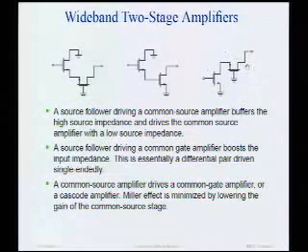And essentially, this second device is just acting as a current buffer, and takes the current gain of the first stage and translates it to the output, and also provides some more voltage gain, which you're not getting from the first stage now.